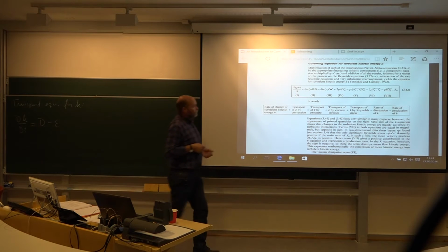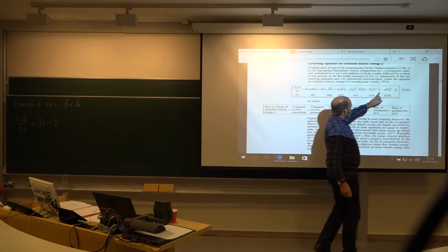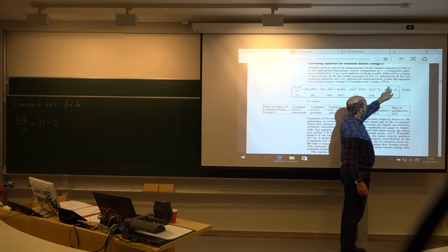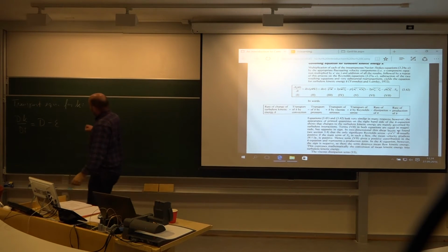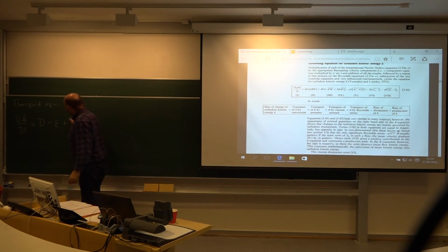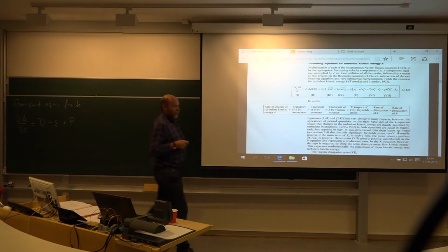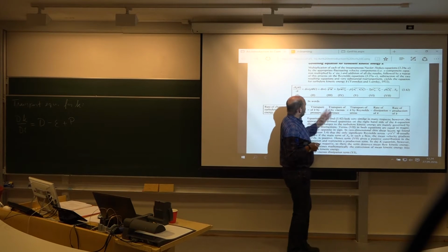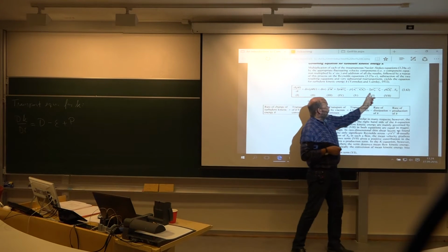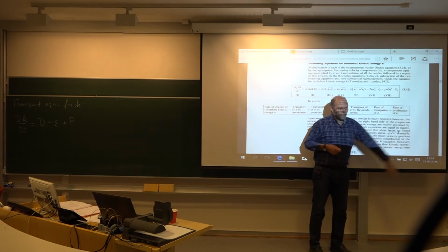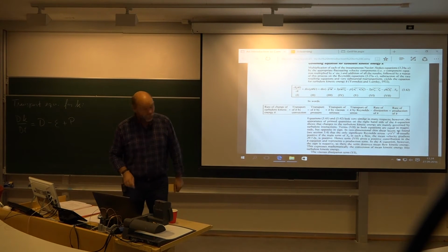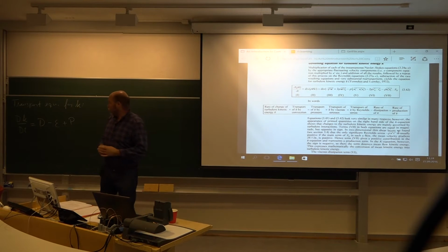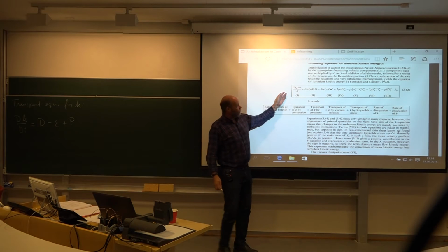The last term is actually negative here, but this is going to be mostly negative in a real case. So it will actually be a production term. You might say everything else that has not a derivative in front nor a viscosity, call it production. Simple. So you can start with this equation instead of this one.